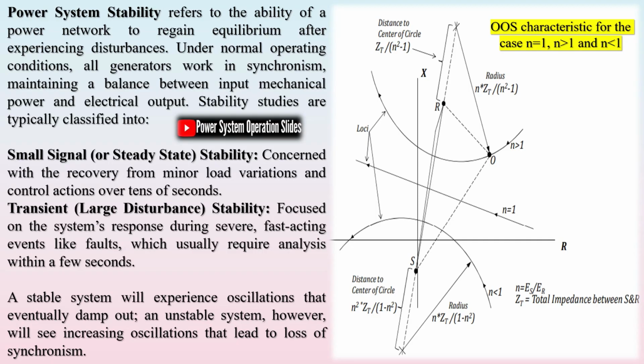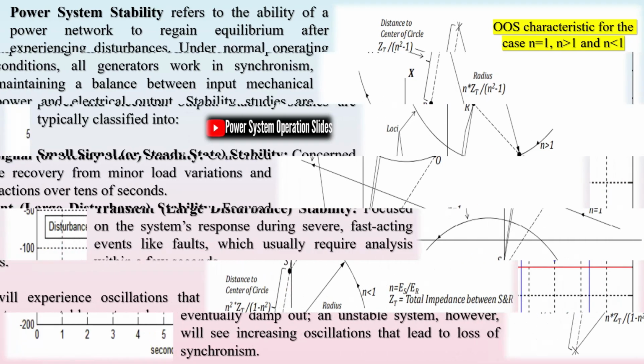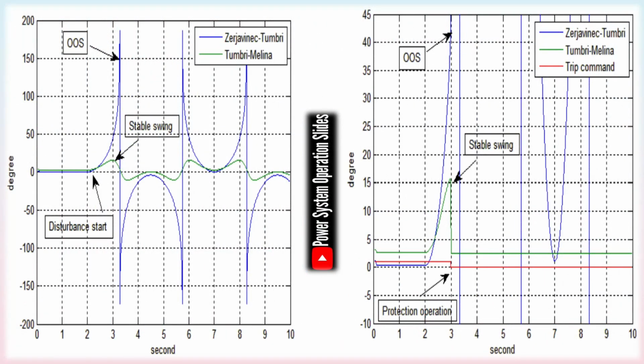Turbine control mechanisms, such as power load unbalance protections, can activate during system disturbances or load rejection events, but these should not be mistaken for an OOS event. Overspeed typically occurs after pole slipping, whereas an undetected OOS condition can eventually lead to overspeed. This makes dedicated OOS protection relays essential.